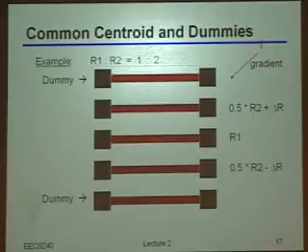And let's say that it was a linear gradient, so that as you walked on planes like this, you had some variation in the resistance. Let's say some variation in the width or something like that. Okay? Now, you'll notice that the way these things are drawn, they're totally symmetric along the x-axis, right? So whatever component of variation there is in the x direction, just by nature of the way the resistors are drawn, that would automatically work out, right? Because even if I had something that was thin there and wider there, they would all have that same shape, right? So they'd all match each other from that standpoint. So now the only thing we really have to take care of is this gradient in the vertical direction, okay?